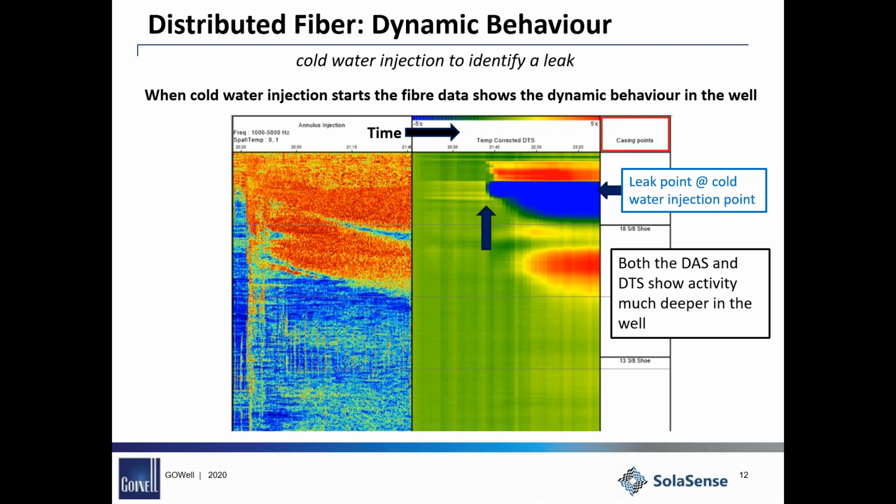It's fair to say that in most fibre surveys, while there is a reason why we go into that well to make a measurement, almost always or very frequently we find something else about the well that we didn't know about. And in this case, there are clearly activities going on deeper in the well that the operator wasn't aware of. And that comes out in both the temperature and the acoustics.